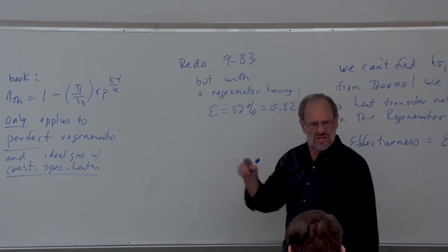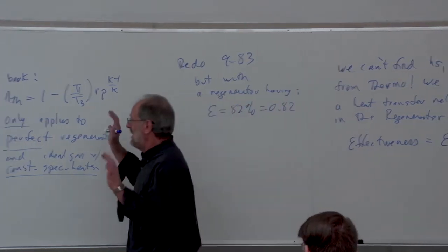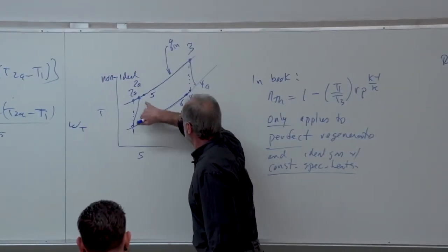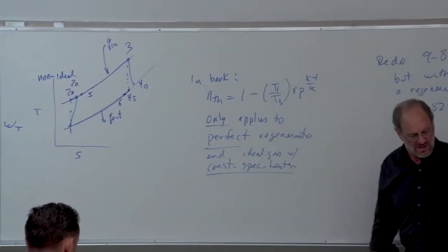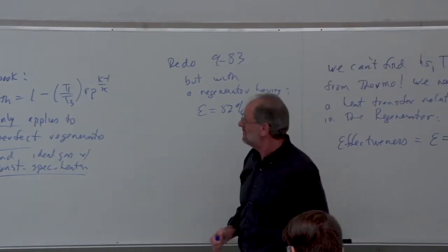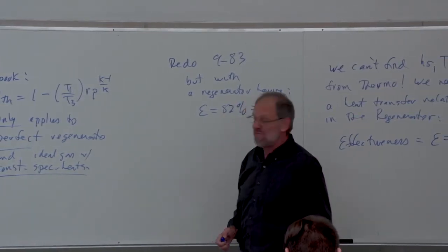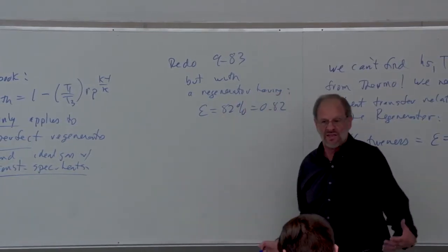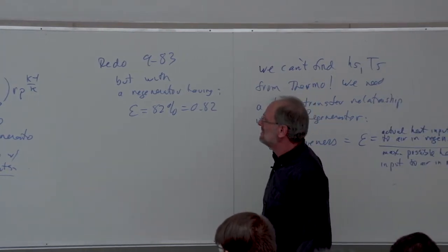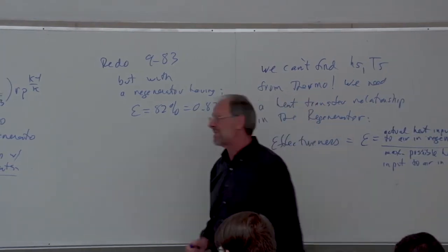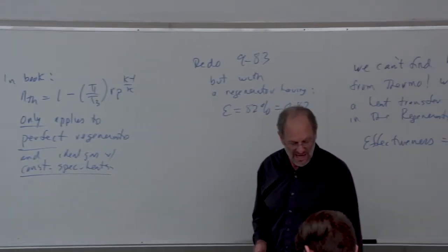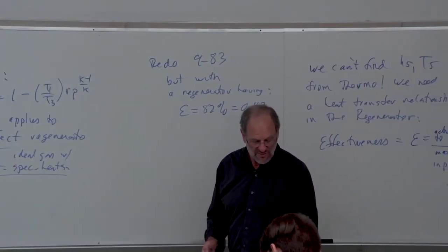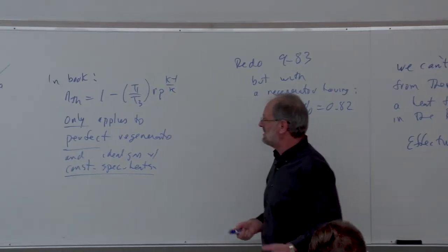We did do a non-ideal case, right? So yeah, this would be identical. There's no difference. So we still are finding the data at 2a. So that's identical. From 3 to 4, also identical, right? Nothing has changed in the expansion from the turbine. Still have the same inlet conditions, same pressure ratio. We still find enthalpy at 4s and enthalpy then at 4a using the appropriate isentropic efficiency. So nothing is different, okay?